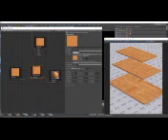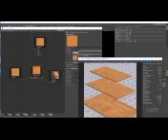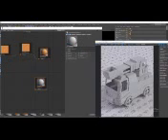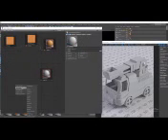I'm going to hide these planks and unhide the truck. In the material editor, create a new Corona material and assign it to the truck. And the next map here is this Corona wire. Let's load it and connect it to the diffuse color.